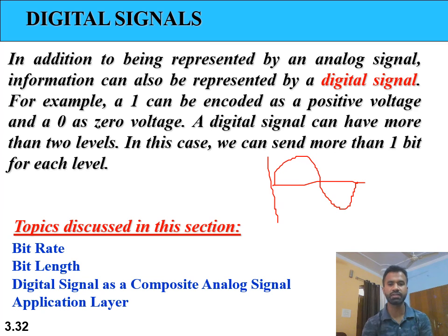Now in digital storage, what we did is we quantize the signal into some levels. If we quantize into only two levels, high and 0, forgetting about the negative value, then there are two levels, a high value and a low value. So I am just quantizing my information into high and low. That high value can be represented by any digital representer, and similarly the low value. In a digital system, the high value representer is generally 1 and the low value representer is generally 0.